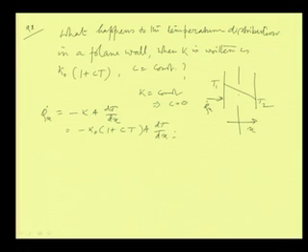Everything we discuss here is in steady state condition and one dimensional heat transfer; these are the two important things behind all the discussions. When there is steady state, the heat flow rate Q dot X will remain constant.